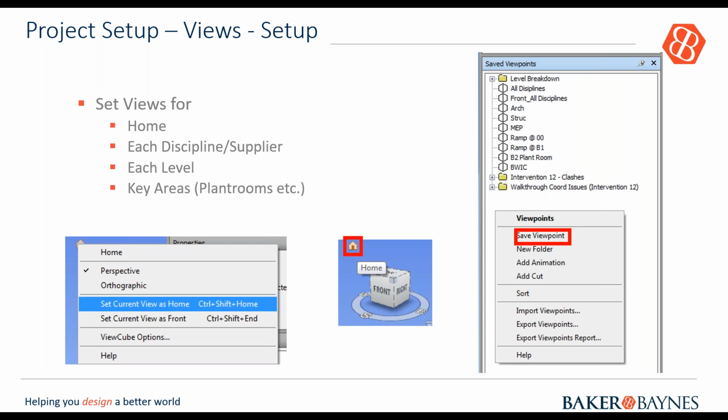After setting that up, to make your life easier as a coordinator, you need to go in there and create different selection sets, right? And selection sets can be generated by types of objects, by levels, as long as you know what you're creating, what you're doing coordinations with, as long as you know the disciplines you're using for your coordination.